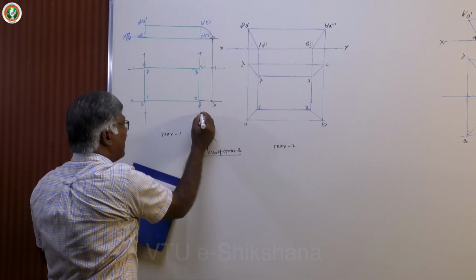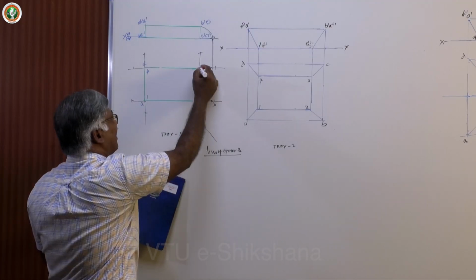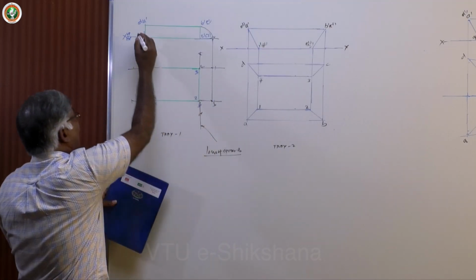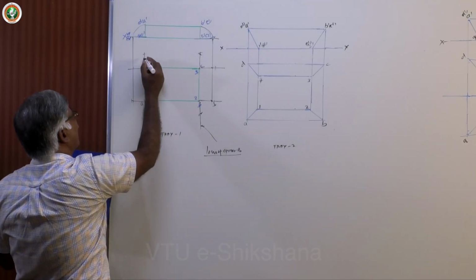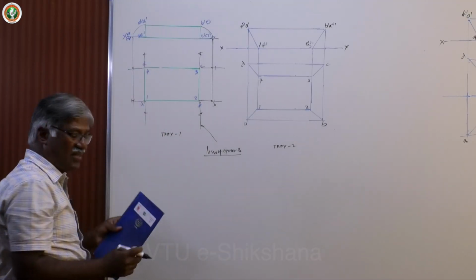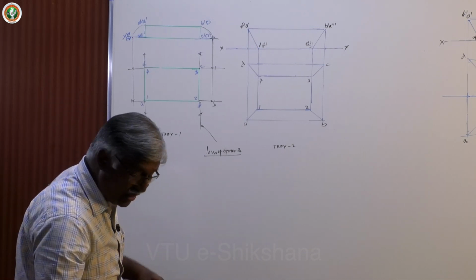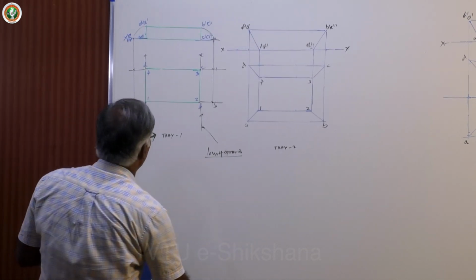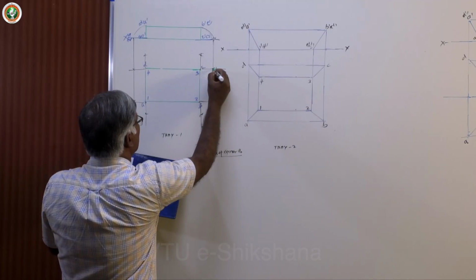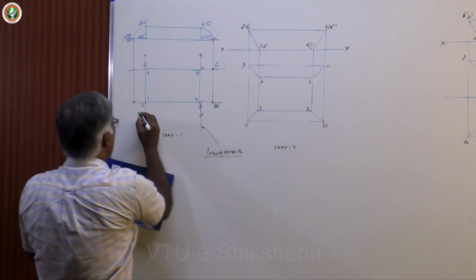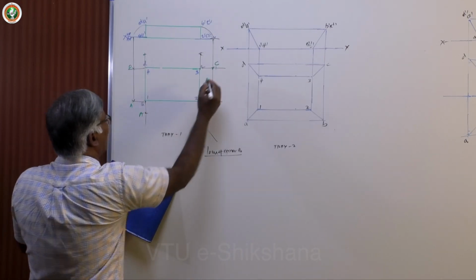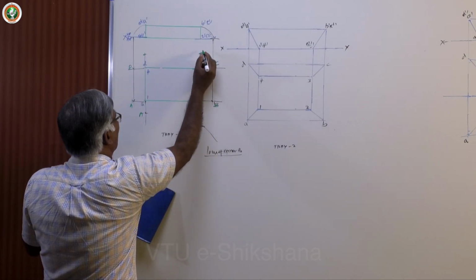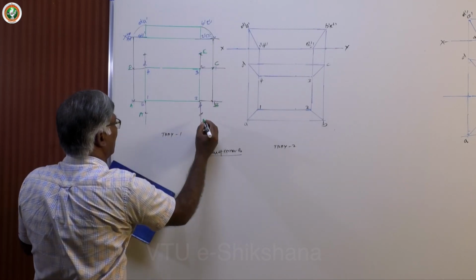Now you take compass, 2A center, this as radius, draw arc. Again 3A center, draw arc. If for a particular one, you can rotate this also and project. Otherwise, you can take compass and then mark here. All these points are easily available now. Now the final projection is this. B, this is C, capital C, this is capital B, this is capital A, again this is capital D, this is capital A. Again, why capital? This is actual points, corners on the flat surface. This is C, okay, this is B.